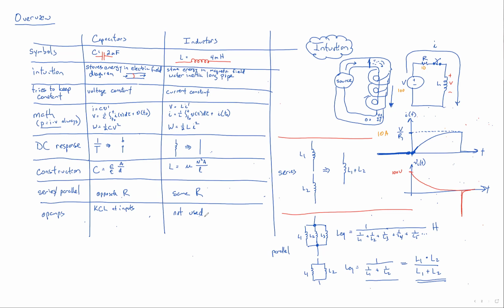Capacitors are crazy good. They're really small physically. As Kyle pointed out last class, their electric field is tightly limited right to where those capacitors are. It doesn't leak beyond the capacitor, so they don't interfere with each other. And real world capacitors are amazingly close to these ideal capacitors we've been studying. Yes, an actual real world capacitor does have some series equivalent resistance, and it does have some non-infinite parallel resistance. But this thing is usually measured in mega ohms, and this thing is usually measured in milliohms. And so it's really, really close to an ideal capacitor.